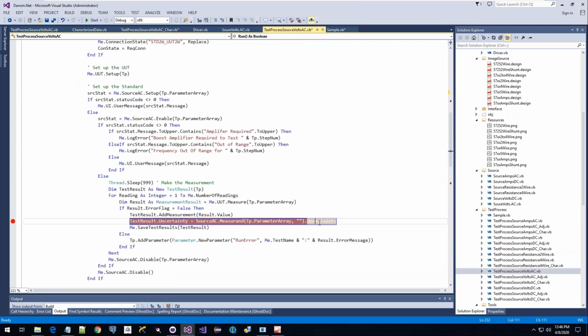And now you can see inside of here, we're going to pass those uncertainties, but we're putting them in the test result. So the test result is also going to have from the UUT the repeatability of the number of measurements and the resolution that was set in the data point, so we can write that data back into our uncertainties. The only thing missing here for a 17025 calibration would be the traceability uncertainty of my calibrator. That would be something that we'd either have to code in or override. After I go through the drivers, I'll reach back in and show you how we have this set up to override.